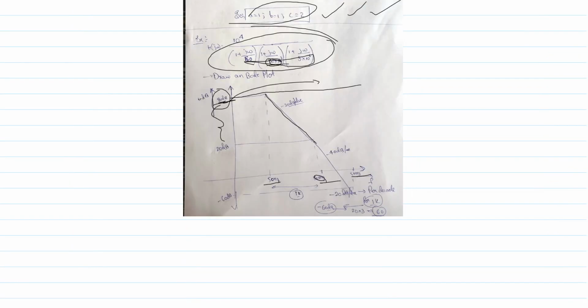After that 50 kilohertz is existing, which is a pole. If another pole is existing, the drop is by minus 40 dB per decade, because 50 Hz gives minus 20 and 50 kilohertz gives minus 20, so totally minus 40 dB per decade. In between, we have to take the y-axis. How to calculate the y-axis degradation? From 50 Hz to 50 kHz, 50 into 10 cube by 50 is 10 power of 3, so there is a drop of 3 decades.